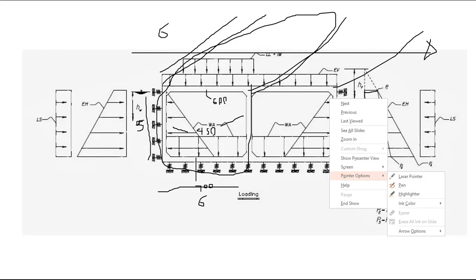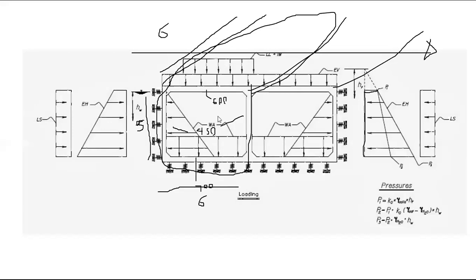Then the force is divided by stiffness. So the soil should be modeled as a finite stiffness element, right? That means it has some stiffness, and you model it as a spring. A spring also has a stiffness. If you model it as a pin, that's wrong, because it doesn't allow any settlements. Okay, so then you will go to SAP 2000.